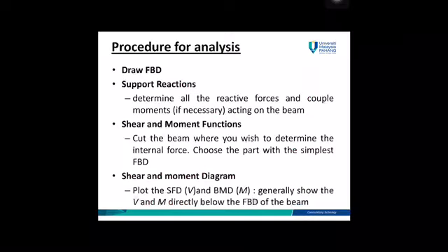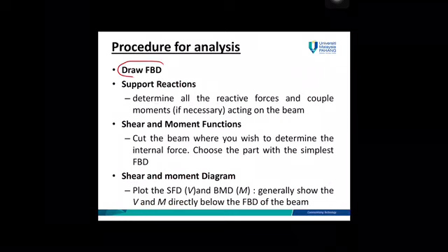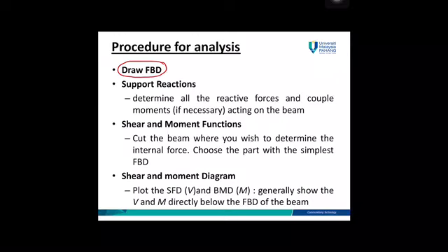First and foremost, the important thing is for you to draw the free body diagram. Okay, and then show all the support reactions, and then by using equilibrium equation, you have to calculate the support reactions value. And then after that you have to cut the segment of the beam in order for you to develop the functions or the equations.